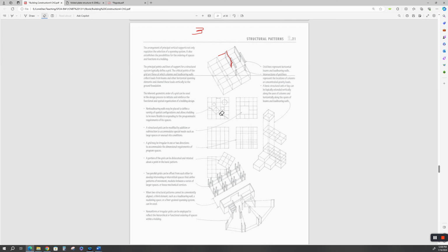A lot of times, architects will start off with a floor plan. What are we going to do with this? What do we want the floor plan to look like? Where do the restrooms need to go? Where do we want the people to flow through? If there are desks, where are the desks? Again, if it's an industrial space with a CNC milling machine, where are the lathes going to go? Where's the EDM machine going to go? That will dictate what kind of structural system. You don't want a bunch of columns in here if all of this is workspace for manufacturing.